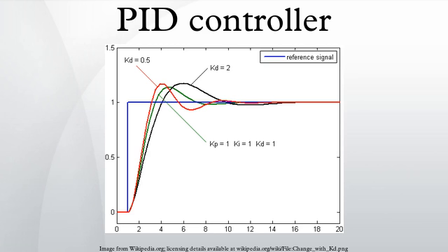In the ideal parallel form, shown in the controller theory section, the gain parameters are related to the parameters of the standard form through the integral and derivative time relationships. This parallel form, where the parameters are treated as simple gains, is the most general and flexible form. However, it is also the form where the parameters have the least physical interpretation and is generally reserved for theoretical treatment of the PID controller. The standard form, despite being slightly more complex mathematically, is more common in industry.